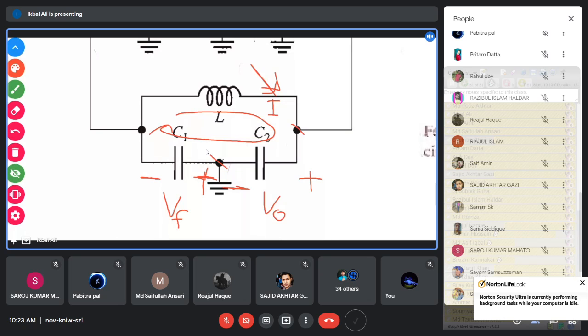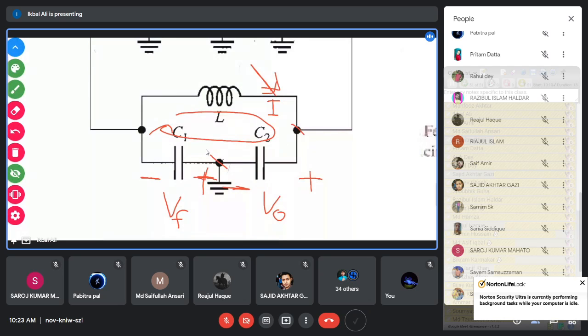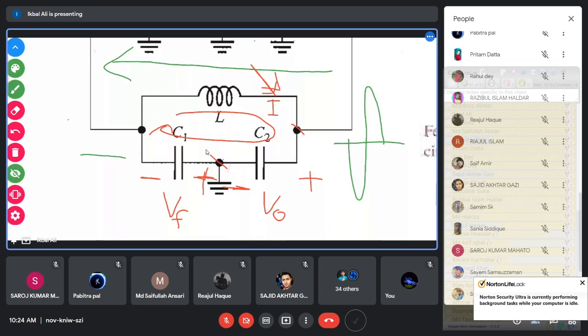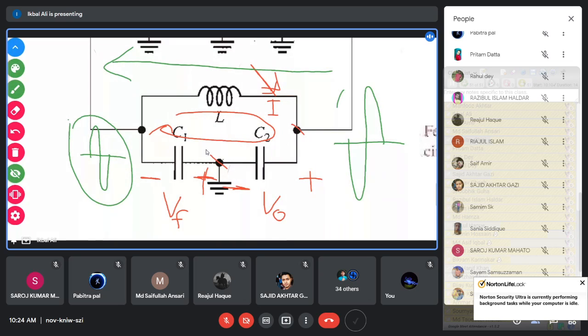Also you can understand how the phase shift changes in this case, how the beta network shifts the phase when the signal travels through it, so that it is 180 degrees phase shifted. If the output voltage is this one, which is the input of the feedback network, then at the output of this beta network, the feedback voltage will be reversed. You see that the feedback voltage is just the reversal of the output voltage, because there is a 180 degree phase shift when the signal travels through the beta network.